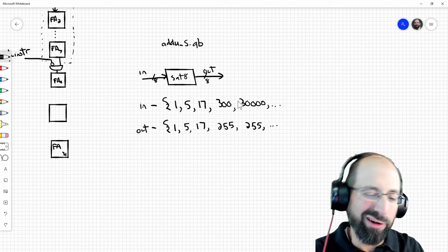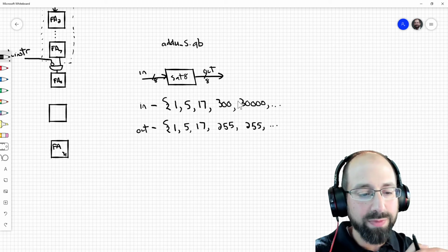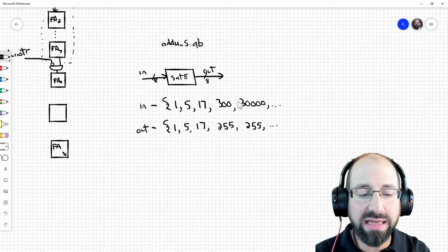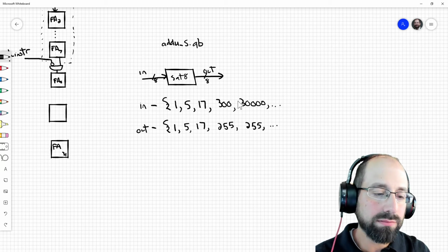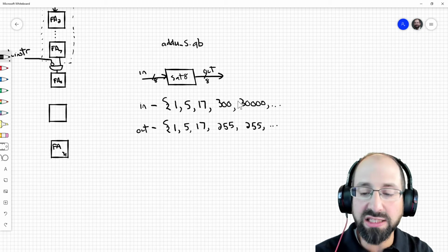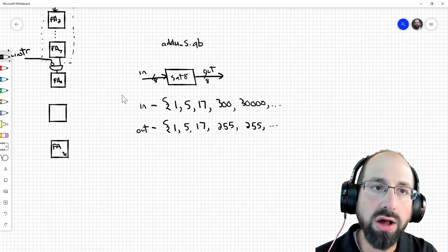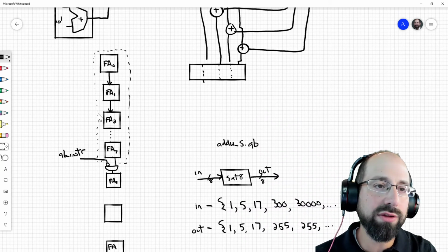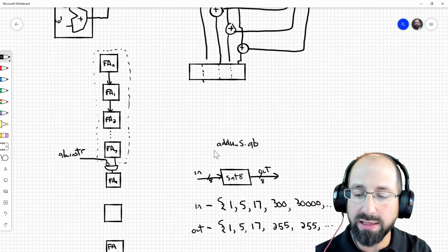There's a little bit of circular logic here. If my input is 8 bits, how am I storing 300 in? But let's assume we have an input that is meant to represent an 8-bit quantity for this circuit, and it's too large to fit inside that 8-bit quantity. The output of our saturating adder, or any sort of saturation operation, would be, instead of the value itself, grab the maximum possible value for that 8-bit data type. And that's actually also not too difficult to implement here. We already have our full adder that's doing the quad byte addition, so that part of the instruction does not change at all. We're still doing quad byte addition.